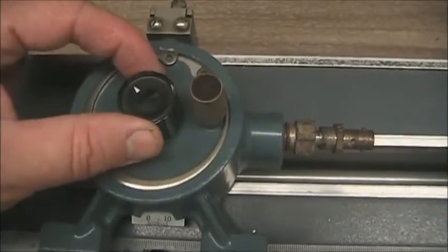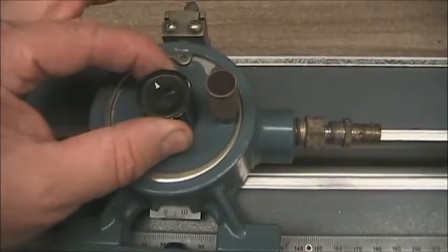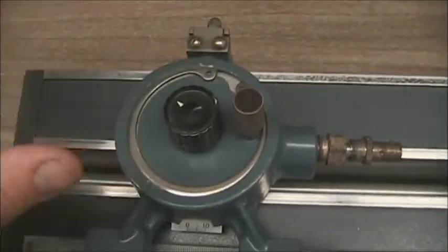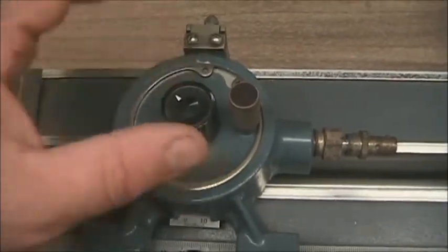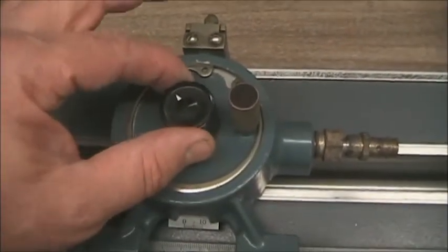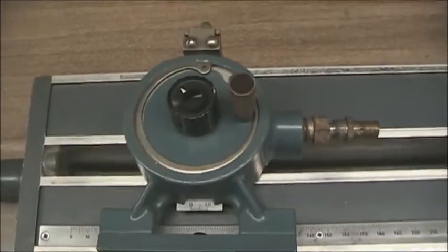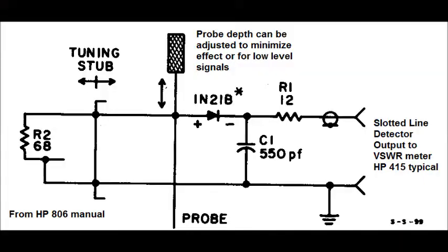This large knob on top is a tuning knob. When you read the handout, you'll see that this is equivalent to an LC parallel circuit, and we'll use that knob to tune for the given frequency. This unit had to be tuned for a specific frequency.